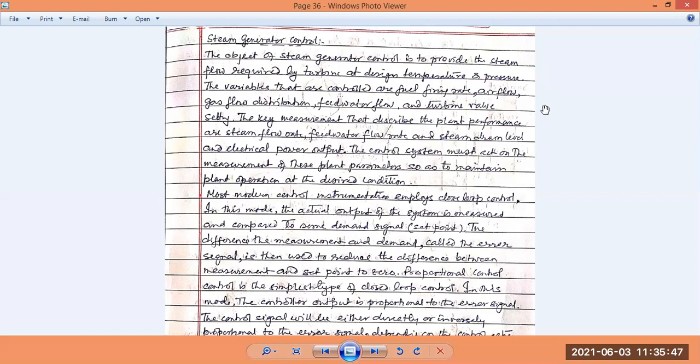It also varies from fuel to fuel, even from one grade of coal to another grade of coal. In a steam generator, we are generally using coal as the fuel. But not all coals have the equal ignition rate. So we have to control a specific air-fuel ratio to make a required rate of firing.